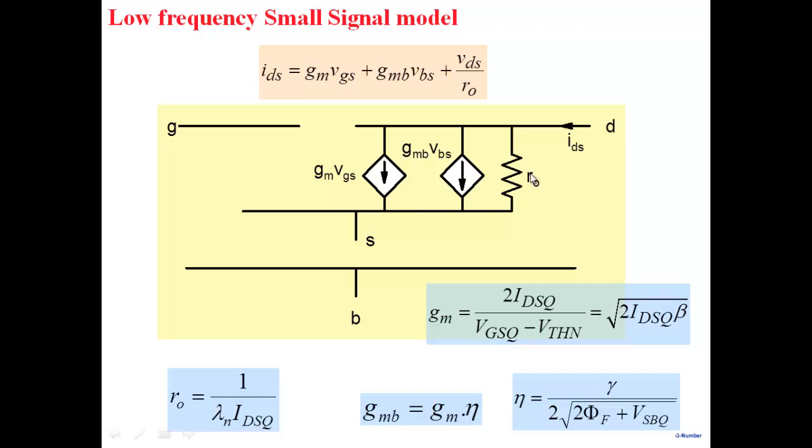Now note that in the small signal approximation, where do the errors arise? Because you're taking a nonlinear expression and linearizing it, right? So which is a nonlinear term here? If you recall, if I'm looking at the MOSFET in saturation region, the drain current varies with the gate to source voltage quadratically. So it's a quadratic variation, and over a small region I'm approximating it by linear, right? So that's where the approximation comes in.